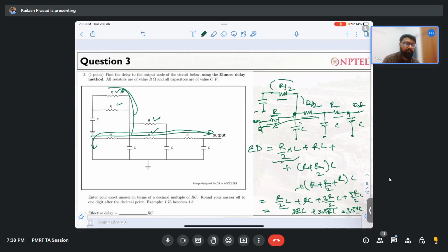You have to keep this in mind whenever you design a circuit. A lot of non-linear effects also come into the picture. So if you calculate some delay using the Elmore delay equation, and some delay using a Cadence or SPICE level tool, you might observe small deviation. That small deviation will come due to the nonlinearity in the circuit.